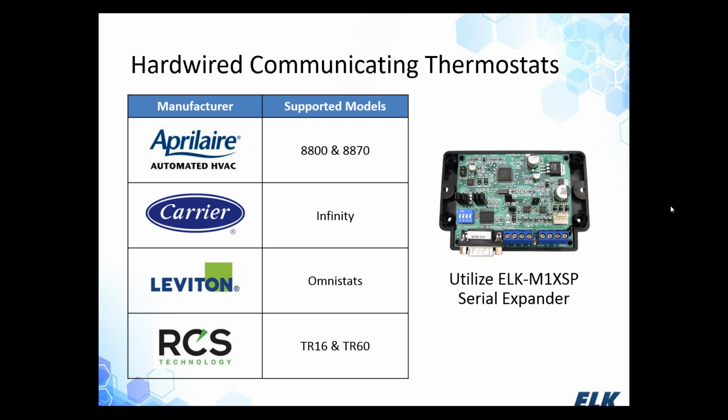That's a lot of man hours, especially if you think about this in a commercial setting, where we've got our offices up front, maybe light manufacturing going on, and we also have a shipping department. We've got all these different thermostats. Instead of having somebody run around and make sure this person turns off this thermostat, how about we just write a rule that connects all these thermostats together and automatically sets those temperatures back dramatically for us. I don't have to think about it. It's just automatically going to happen for me, and therefore we can be a lot more energy efficient moving forward.